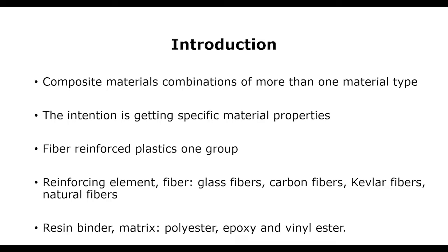And as a binder, these ceramics or fibers are combined with a resin binder. The other name of this resin binder is matrix. There are polyester matrices, epoxy matrices, vinyl ester matrices. These are commonly practiced thermosetting plastic groups, but there is also some research on natural matrices.